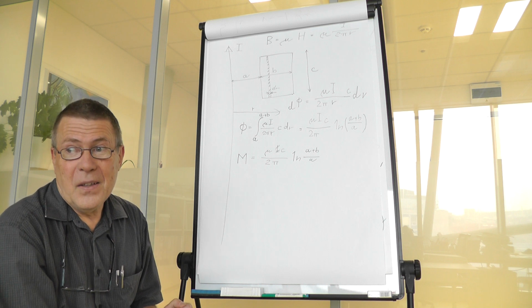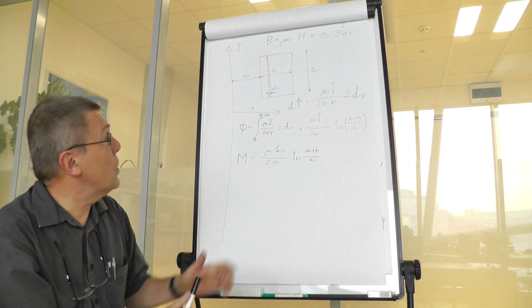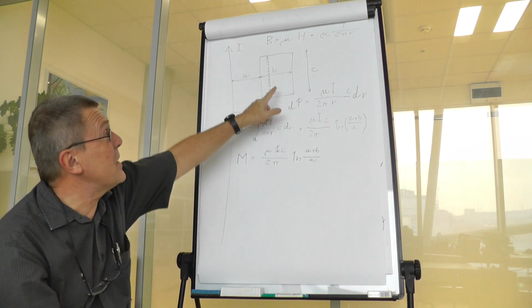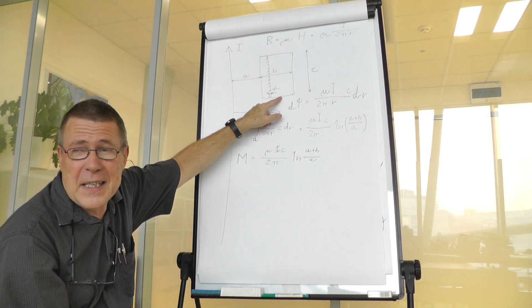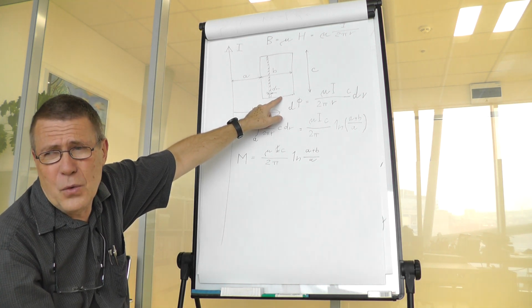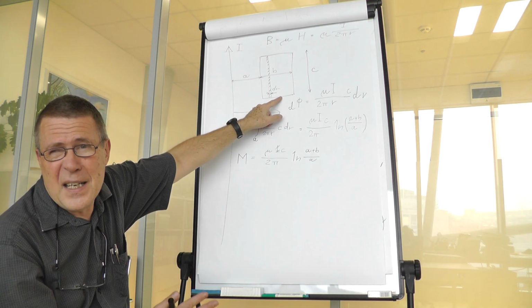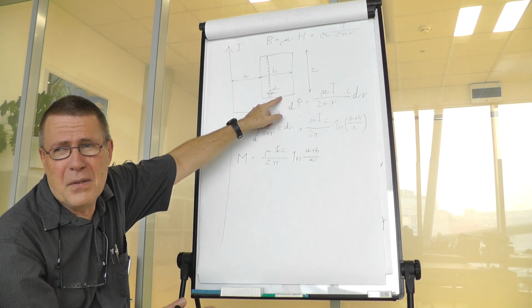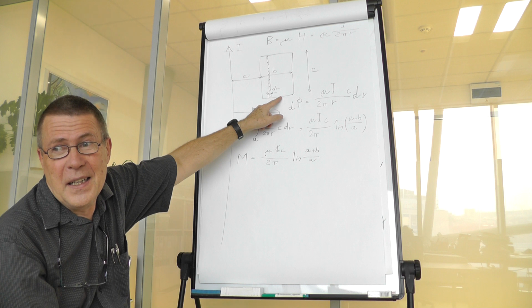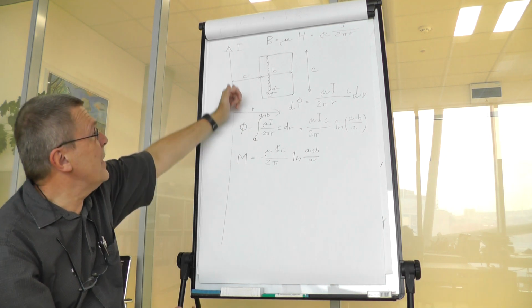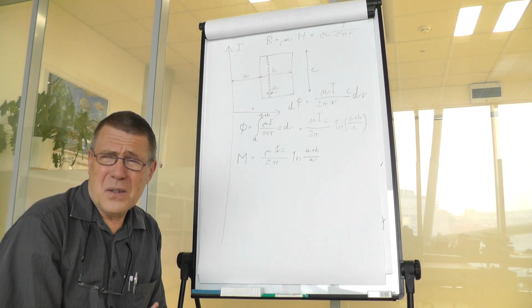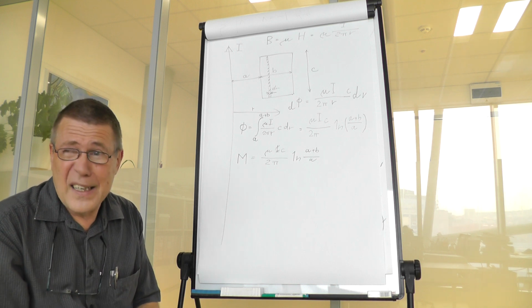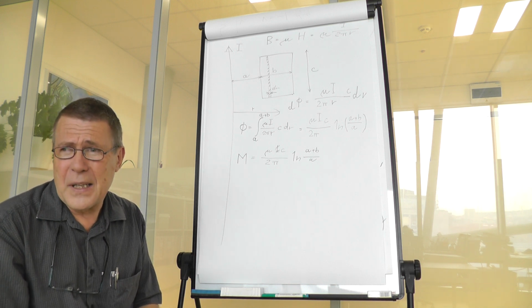But if you want to listen, you can do one thing, and that is to add more turns to this device. So if you, for example, would put there 1000 loops, you get somewhere to millihenries, and that would, in the case of 1 kilohertz in this wire, go somewhere to millivolts, and that's something that you can easily detect by a very simple electronic device.